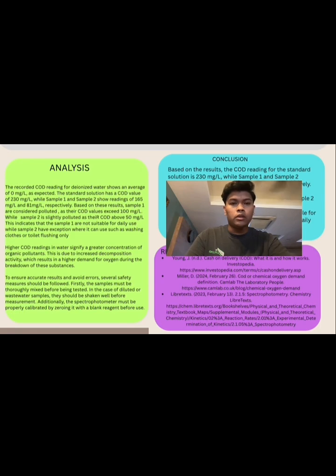So my name is Amir Aswar bin Azrul, and now let's take a look at the analysis of the COD readings. The deionized water, as expected, recorded a COD value of 0 mg per liter. Our standard solution showed a value of 230 mg per liter. When we tested our samples, sample 1 had a COD of 165 mg per liter, while sample 2 had 81 mg per liter. So based on the result,